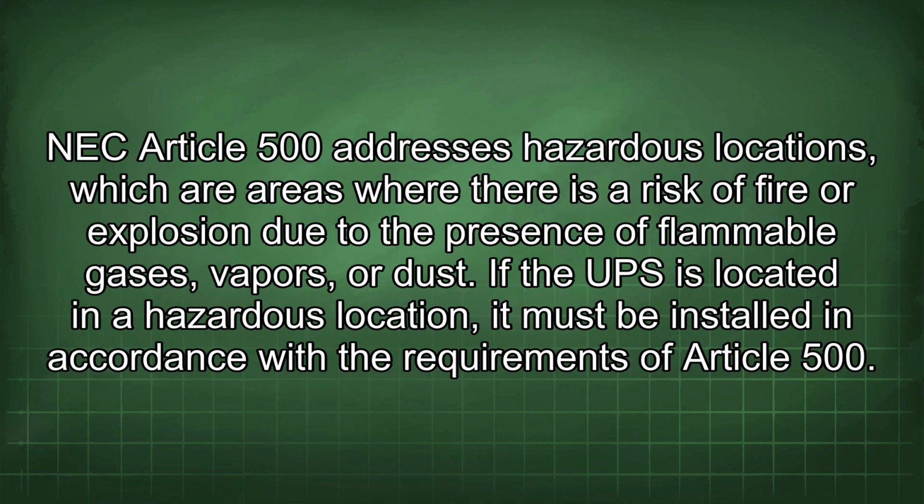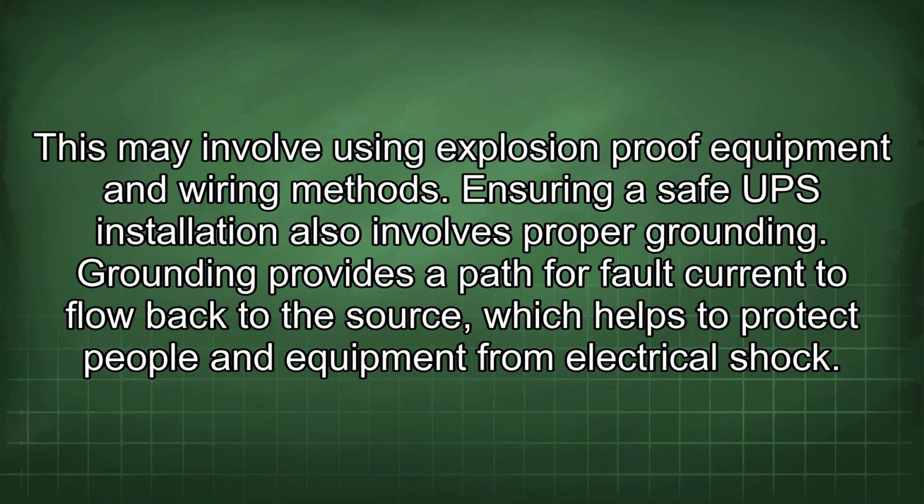NEC Article 500 addresses hazardous locations, which are areas where there is a risk of fire or explosion due to the presence of flammable gases, vapors, or dust. If the UPS is located in a hazardous location, it must be installed in accordance with the requirements of Article 500. This may involve using explosion-proof equipment and wiring methods.